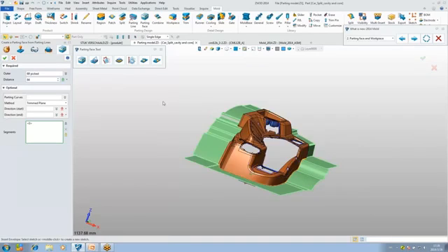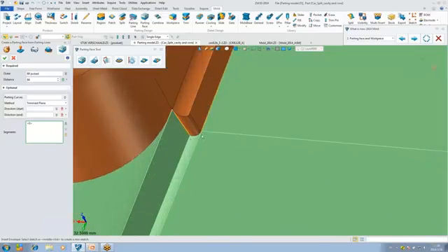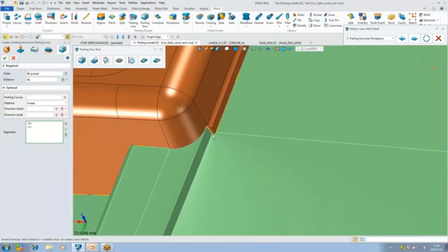Okay, let us look at another pattern edge here. This is actually the corner pattern line, but since it used the two-measure method as the default, it creates two faces here. Using the new version, we can select it independently. Just select it, change it to use the sweep function, and also define the direction. And middle click. You can see that it's very quick to collapse this face for the product model.